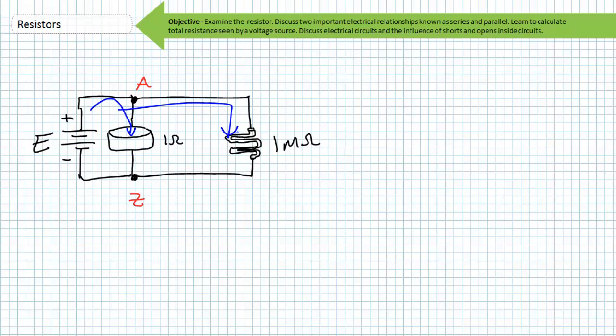Granted, only one electron out of 1,000 is going to take the time to grease itself up and get down on all fours and wriggle through that narrow, twisted passage. The point is that one electron now has an additional opportunity to travel through our circuit, where previously the opportunity did not exist. In effect, anything in parallel, even extremely high resistance paths, always reduces the total resistance seen by a source because it allows more opportunities for current to flow.